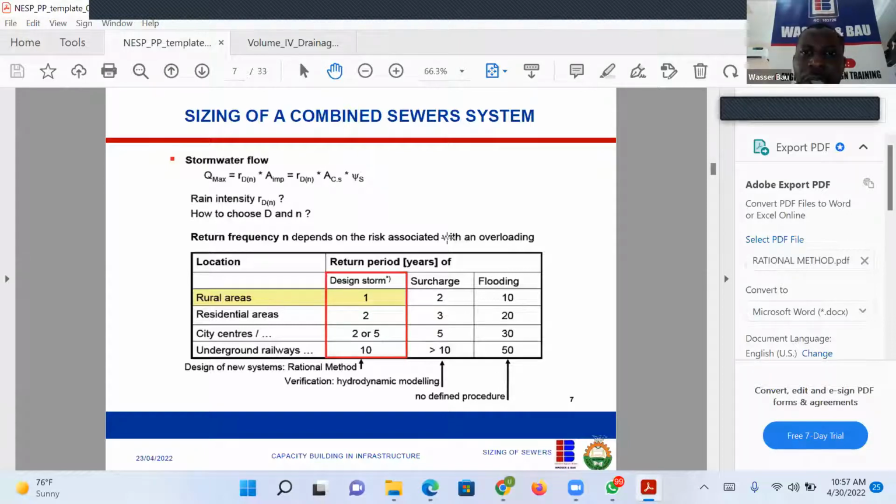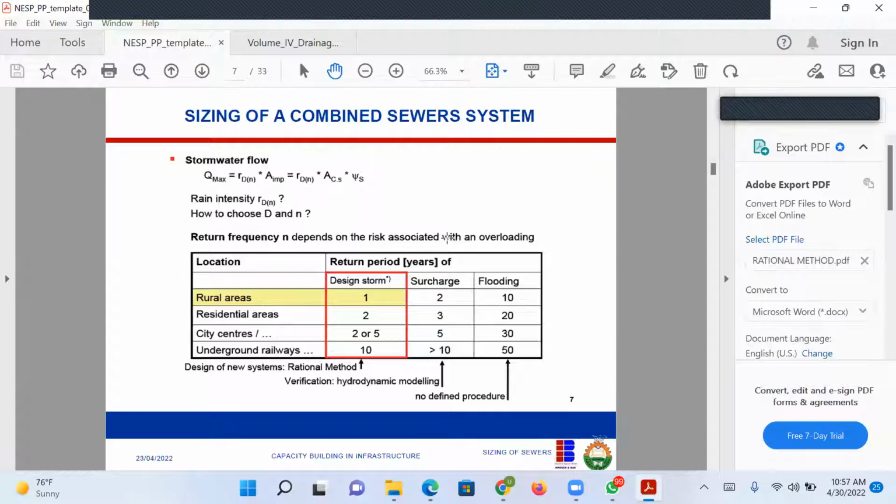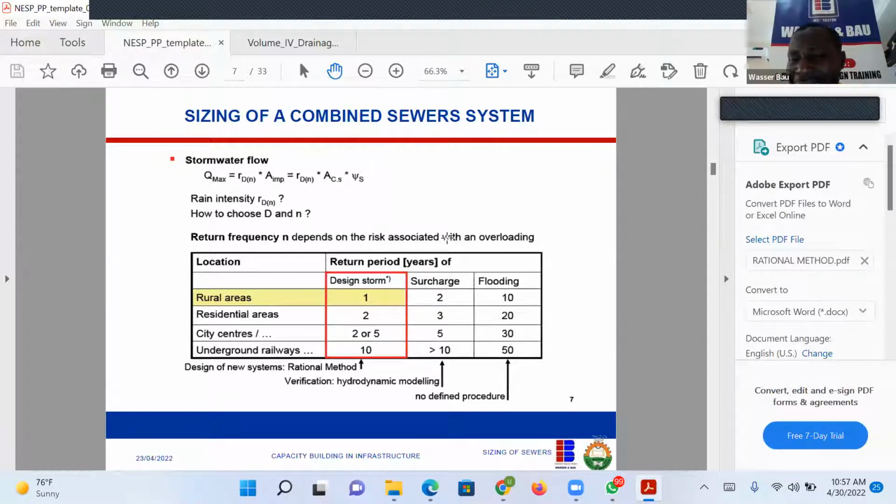Listen to this. He said, you know that all these outskirts are not well regulated. When they start building houses, all of them will use interlock, and they will flood everywhere. So I was able to persuade him to use a lesser value, I think we finally used 0.6. Because by the time we started using 0.7 as peak runoff, meaning that 70% of the flood will come to the drain, we found out that the drain sizes were so huge that when I drew his attention to it, it came down to 0.6.